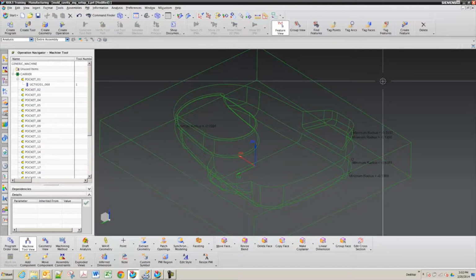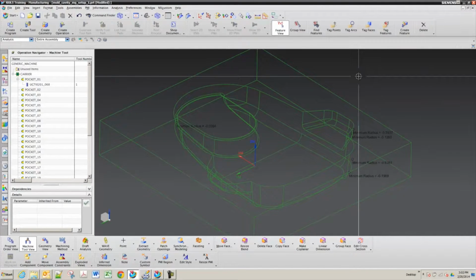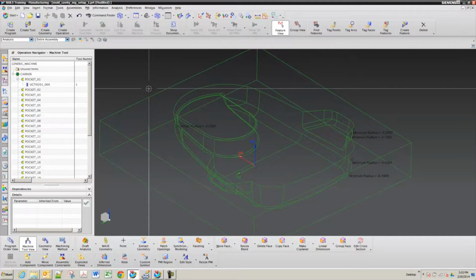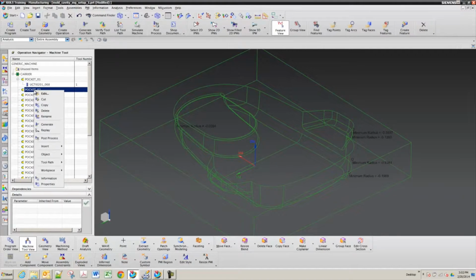Would you route this out with a ball mill so that you already have a radius? Well, we have to do the top. We got the flat. Then what do you want to add for the inside? You want to do a ball, or start with a flat? Okay, what's like a half inch? Yeah, I'd use a half because this one's small.